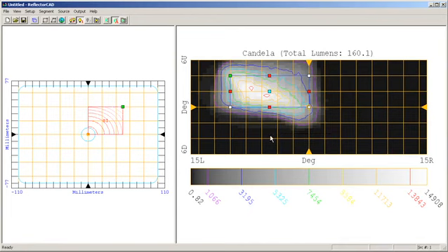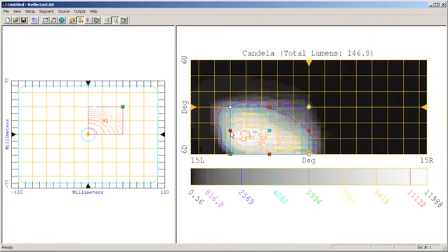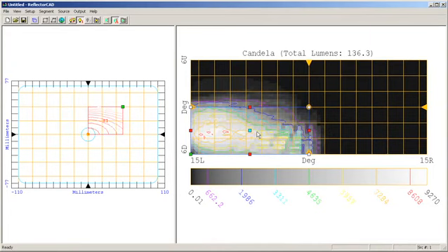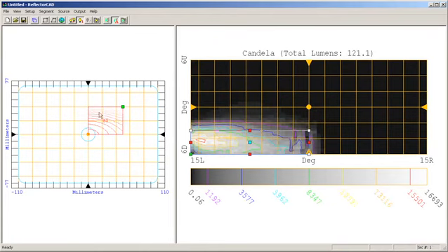In fact, what I will do is actually come over and operate on the luminous intensity pattern, changing that pattern to the desired shape that I want from that particular segment by dropping and dragging the various areas around the luminous intensity pattern, and ReflectorCAD will automatically update the shape of the segment in order to produce that particular luminous intensity pattern. Now, in the segmented area of the display screen, you will see a series of contour lines in the particular segment. What this indicates is whether this new segment is above or below the base surface that you've identified.